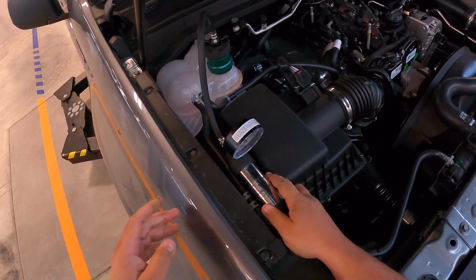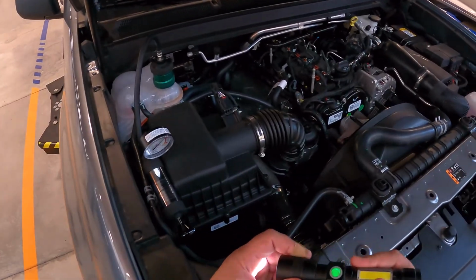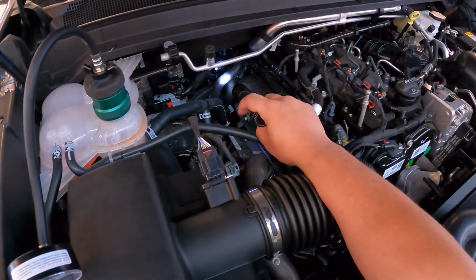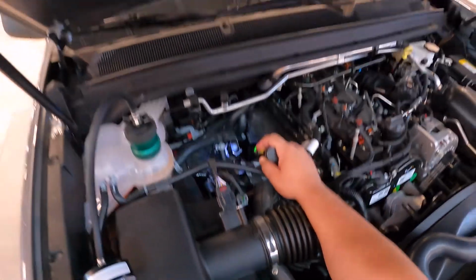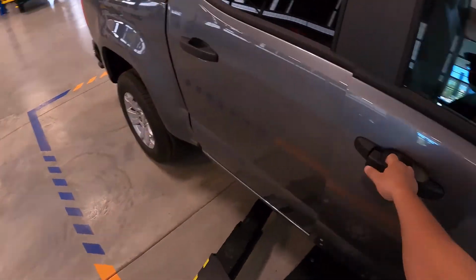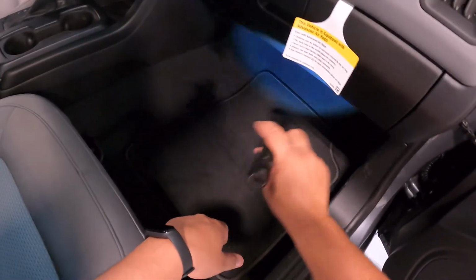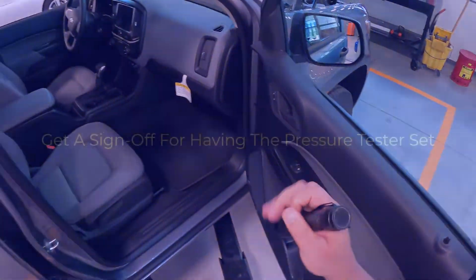Once you get there, go ahead and set your pressure tester down, grab a flashlight, and now we're going to look at the lines going into the heater core, which are right back here, and we're looking for any types of leaks at the connection where it goes in. Also, we want to check inside the passenger compartment to see if there's any coolant leaking here. Is the floor wet? Does it smell like coolant, etc.? Because if it's going to leak, that's where it's going to leak.